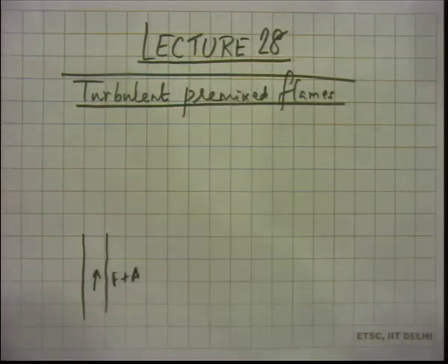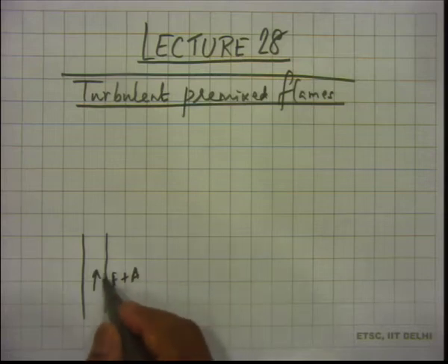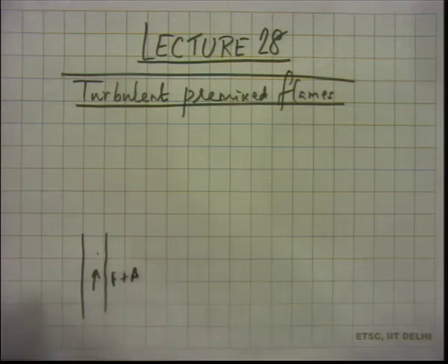and that is at a high enough velocity, and the flow has some disturbance. So, you have turbulent flow, and if you set up a flame on this, the flame that you get is a turbulent premix flame, because the fuel and air are mixed prior to leaving the burner, and it is also giving a flame which is set up in a turbulent flow field. So, it is a turbulent premix flame.